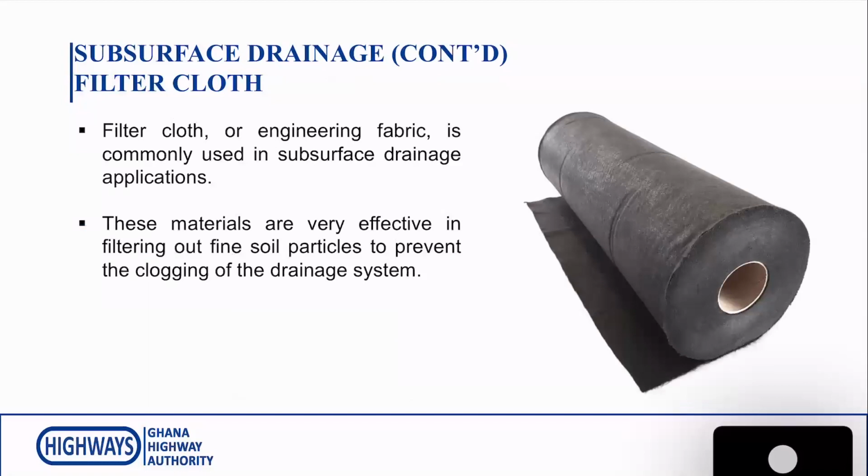Like this. This is what I mentioned, the filter cloth. It's an engineering fabric that is commonly used in subsurface drainage. So for example, after we have placed the coarse aggregates on the perforated pipe, we'll put this filter cloth on top of it before we place on top the natural soil material. And it's supposed to prevent fine materials going through and clogging the perforated pipe, as well as the stones that we have laid.